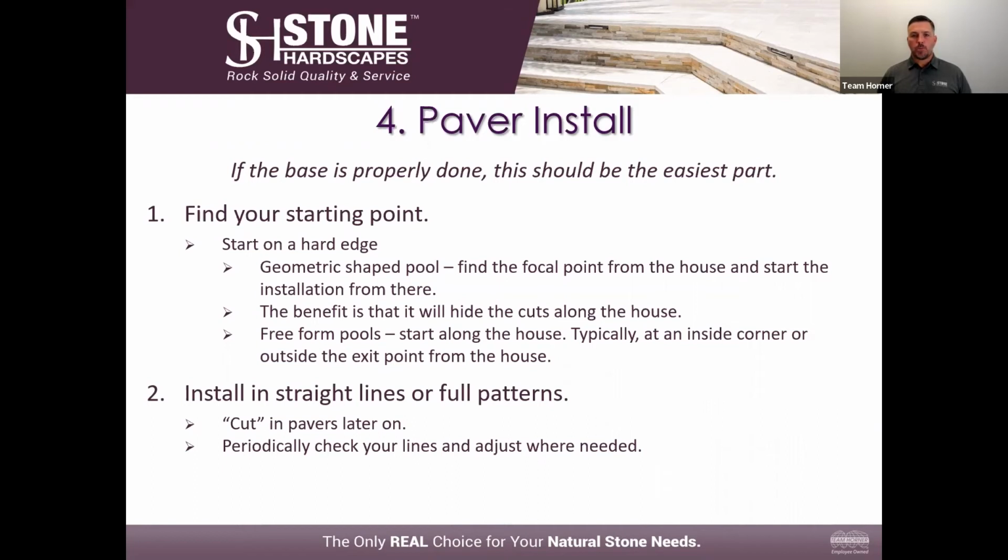They'll have 2 people laying the pavers themselves. And as they get around roughly halfway done, someone will go back and start putting the cuts in. But if you start trying to lay the cuts as you're installing the pavers, the time it's going to take to do this is not going to be cost effective. So you always want to lay pavers on a straight line.